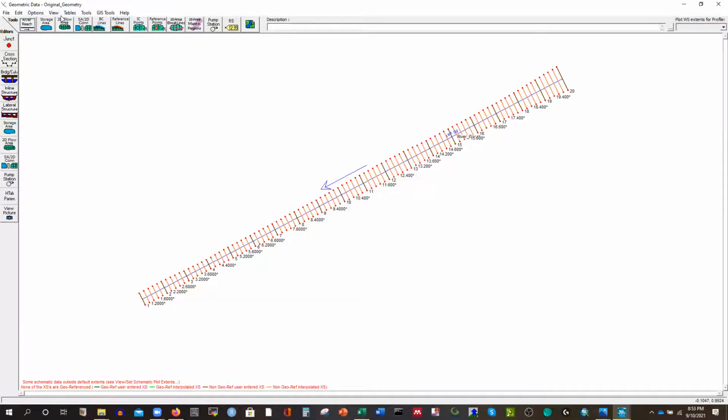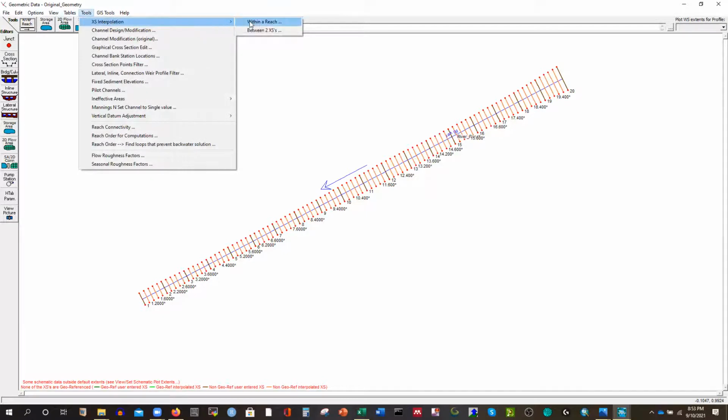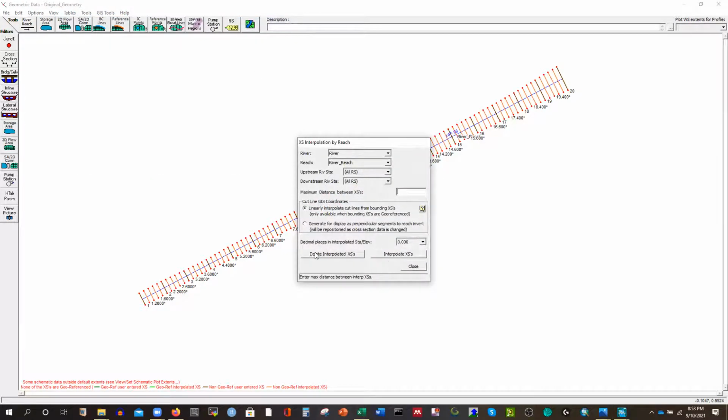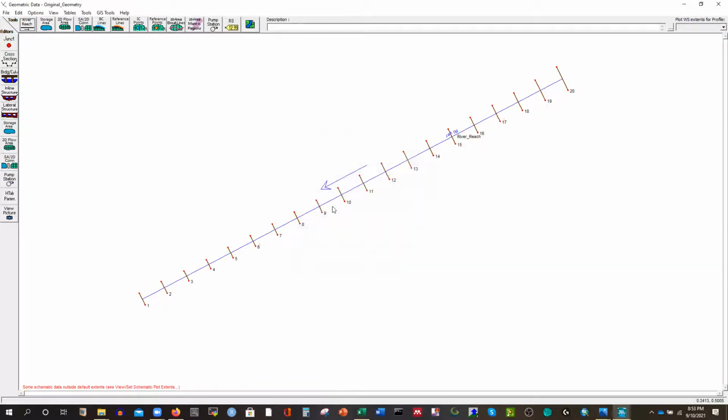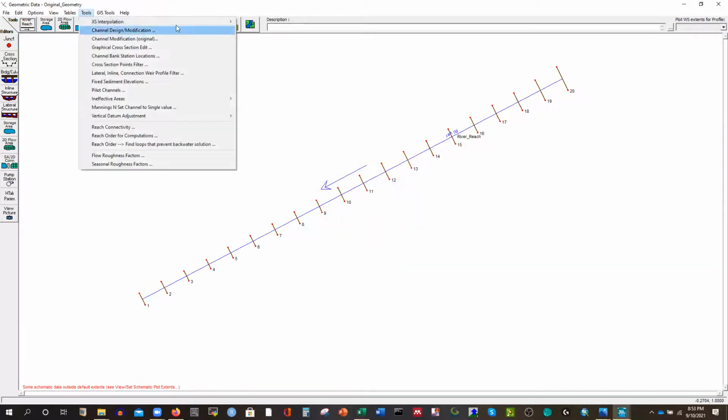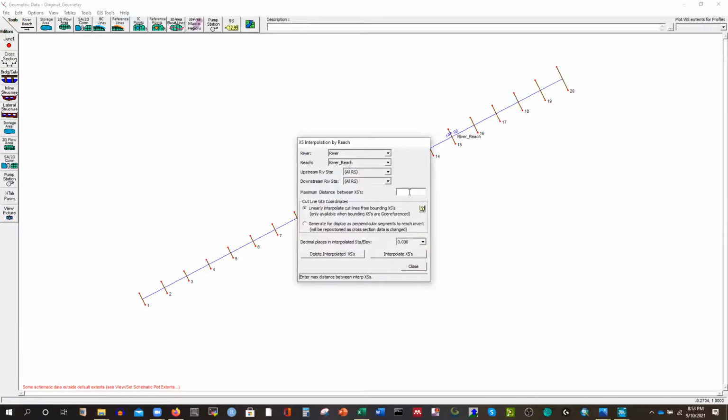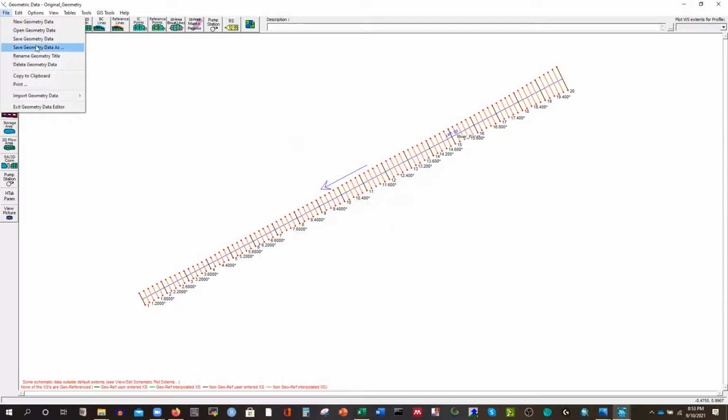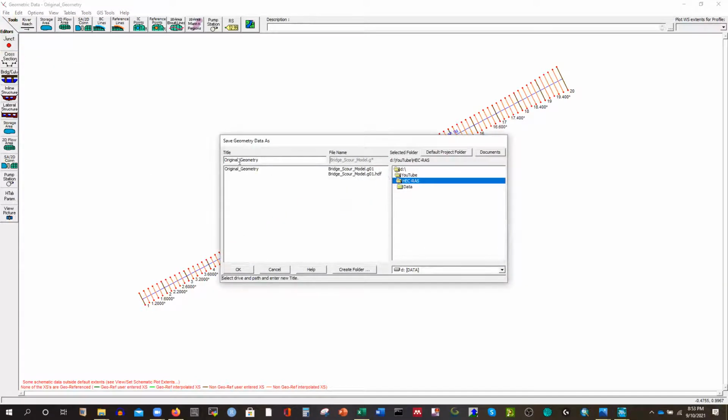If you think, okay, I made a mistake here and I'm going to delete it, you can do that. Go to interpolation and then section and delete it. Okay, then it will be deleted. It will only delete those sections. I'm going to do it again to show you the process. It is only 100 meter interpolate. And now I'm going to save it again, save as interpolated section, instead of the original one, because I preserve the original one so that I can change whatever I need. But for any bridge analysis we don't need to do that. Okay, I'm going to do it.